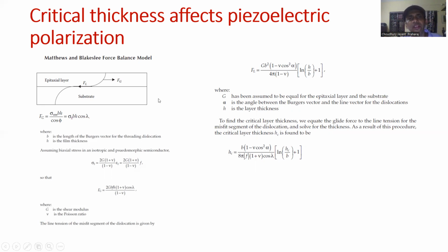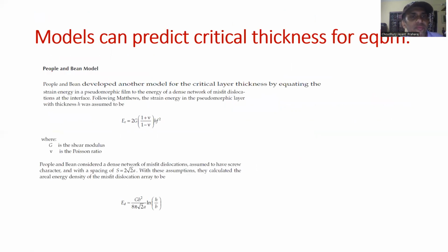So the various force and energy terms that enter into determining the critical thicknesses involve, for example, the different elastic constant parameters in these materials, and then the Burgers vectors, and then the dislocation dimensions, etc. And those enter into theoretical models or semi-empirical models from which critical thicknesses can be determined and then can be compared with experimental values.